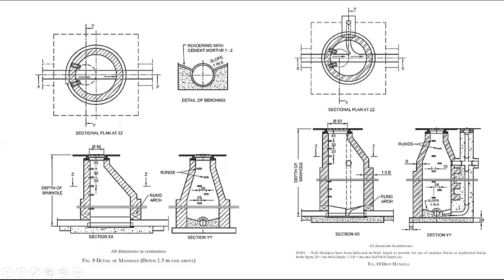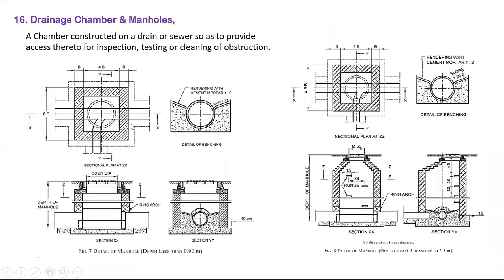Suppose the water is coming here, there is no corner. Automatically this water will pass outside. The food particles or any other particles will also go out. That's all. If you are using a square manhole like this, the particles may be deposited in the corners. All the corners may deposit. After a long time, the deposited particles will get hard.